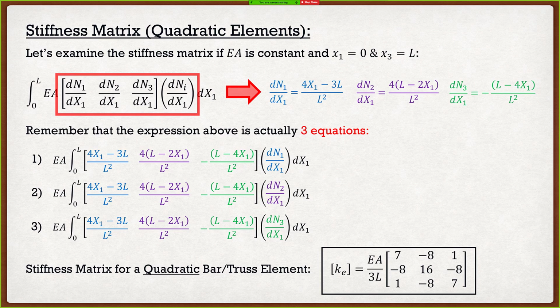You guys are saying, well, hold on, this is a little bit more complex. Yes, it's more complex, but again, you get that increased accuracy. So this is where it becomes up to you as engineers to figure out what you should use: quadratic elements or linear elements? Another thing you will see is this: what happens if I take one quadratic element, which has 3 nodes, and compare it to 2 linear elements, which also have 3 nodes? That's one of the things we're going to have to consider. It becomes kind of funny in that you get different paths. I can either have a lot of linear elements or fewer quadratic elements. You've got to pick your poison, if you will, and try to find out which one is the best.